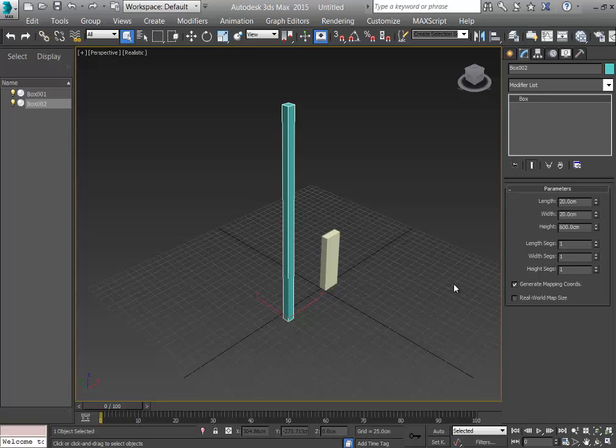So whatever I'm going to build now is going to be built on that box. What I want from here is to implement 2 modifiers on that box. The first and the second, order is important. If you make the first one, for example, bending, then twisting, that means that first of all it bends and then twists around it. If you make first of all twist, then bend, you will have a twisted rod which has been bent later on. So the order of modifiers is important.